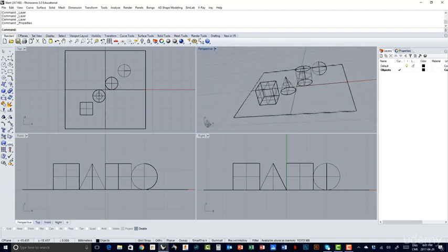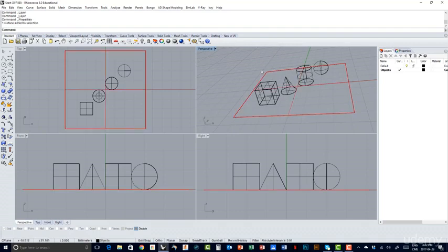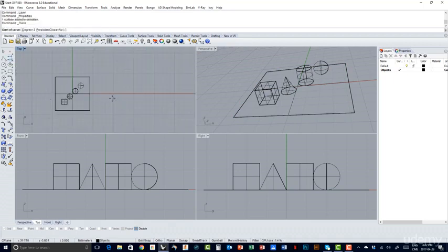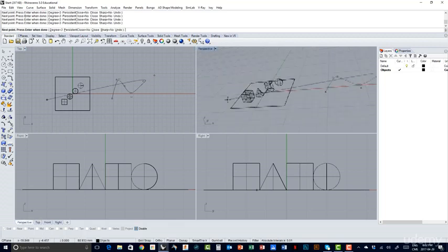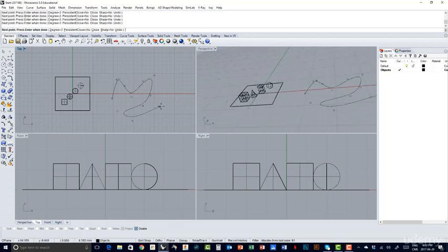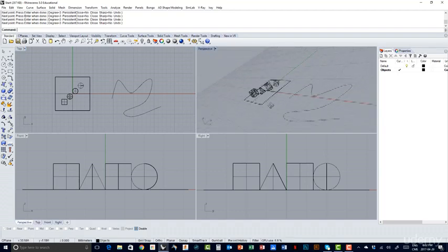So everything works in a coordinate axis based on the X, Y, Z. What you see here, this surface, for example, is lying on the XY plane. If I refer back to the top viewport, I see the XY plane as well here. So whenever I start sketching in the top viewport, like this, if I zoom out here, because I'm working on the XY grid in the top viewport, this grid is the same in perspective. And you can see that it's a fully flat 2D curve. Everything that is happening in the top viewport is reflected here on this grid on the XY plane.